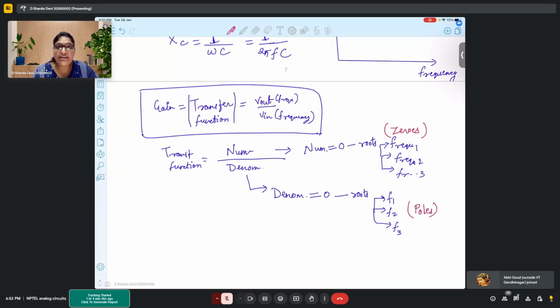It will be a ratio between, say, input current versus input voltage, or input voltage versus input current. All this is possible, but there is no such thing as input gain, because gain is always a transfer parameter, or we can say it's a relation between two different ports. In your case it is always a relation between output and input.